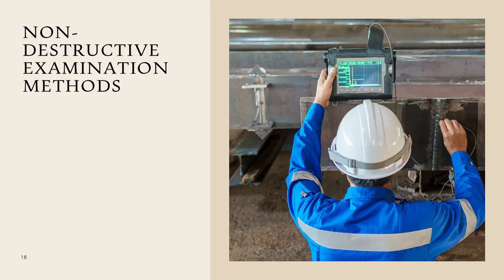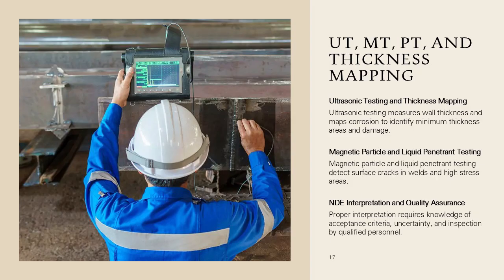Ultrasonic testing, UT, magnetic particle testing, MT, penetrant testing, PT, and thickness mapping. Non-destructive examination methods are used to quantify damage and detect flaws that may not be visible to the naked eye. Ultrasonic testing is widely used to measure remaining wall thickness and to perform thickness mapping in areas of suspected or known corrosion. Systematic thickness mapping helps identify minimum thickness locations and corrosion patterns.